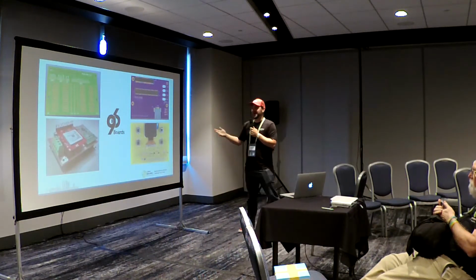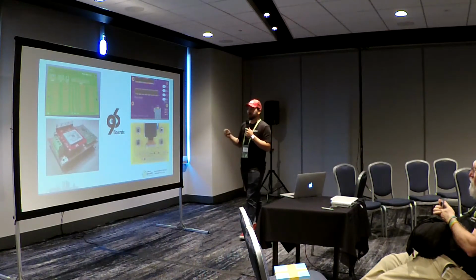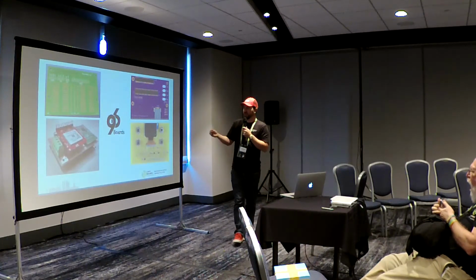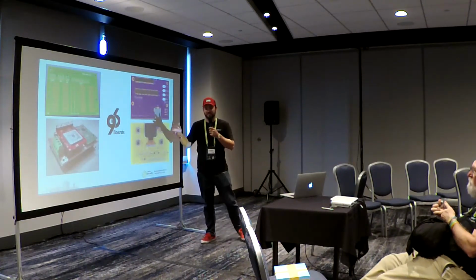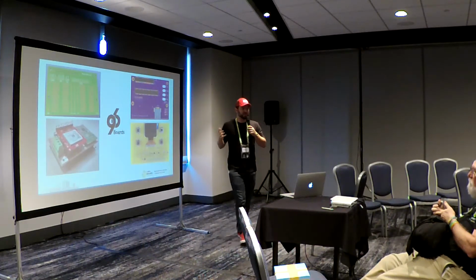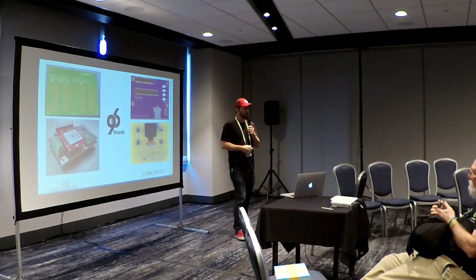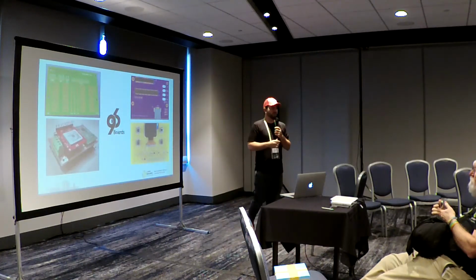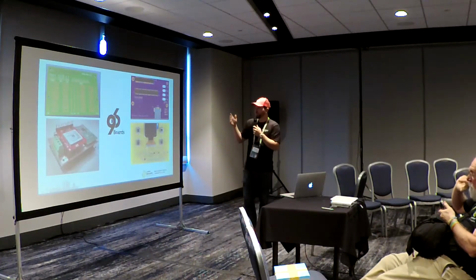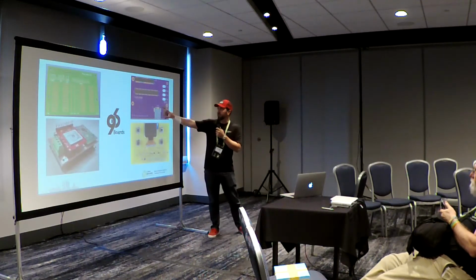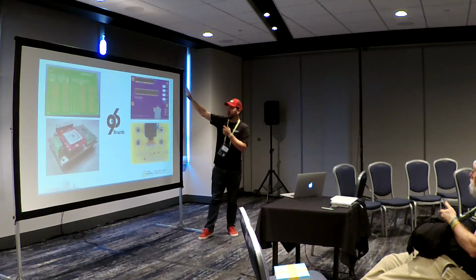Great. Now, I mentioned that this repository, while it's still new, already has output, okay? People have already consumed our templates, and they have contributed. We have a proto-mezzanine that came up here. These are all initial phase mezzanines that are testing the capabilities of what we can do, right? We want to make sure that we have our high-speed and low-speed connectors measured properly, so we're not going to build some super intricate mezzanine and then plop it on and see that they're not aligned properly, right? So some of these are just initial mezzanines. We're testing our ability to tap into the high-speed header. We're testing our ability to expand and do through pins, and our abilities to bring out IOs.